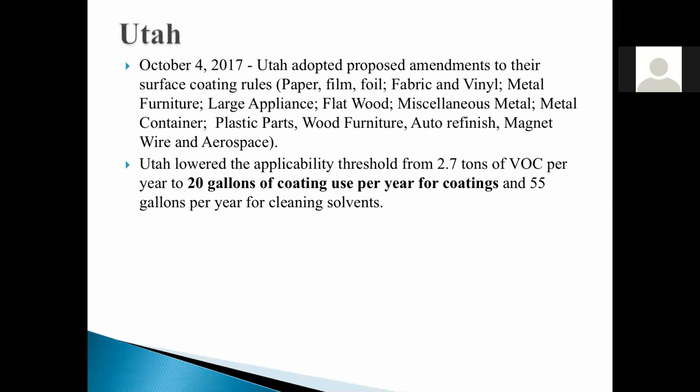I did want to mention that Utah has some severe issues with PM 2.5 and ozone, and they lowered the threshold. For example, instead of being 2.7 tons per year, they went down to 20 gallons of coating use per year. So pretty much every facility in Utah is subject to the limits out there.